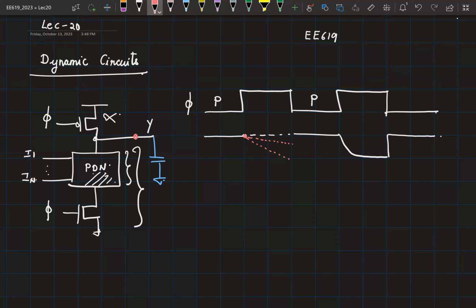So the other solution is the time period which is available for this capacitor to completely discharge without being reinforced through any other mechanism is basically half the clock period, right? So the other solution is to make sure that T clock by 2 is small, or effectively the clock period is small, which means your frequency has to be slightly large, right? That is also true. Yeah. So not really. So what is your suggestion?